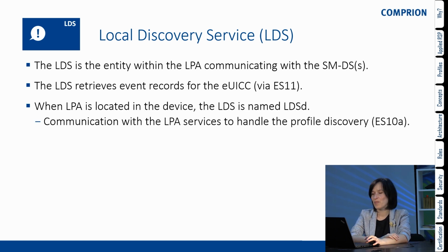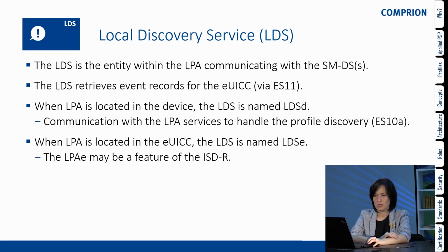When the LPA is located in the device, the LDS is named LDSD, and communication with the LPA services to handle the profile discovery is performed using the ES10A interface. Basically, the idea is to use this interface or local discovery service to discover the profile. When the LPA is located in the eUICC, the LDS is named LDSE. The LPAE may be a feature of the ISD-R, the issuer security domain root.